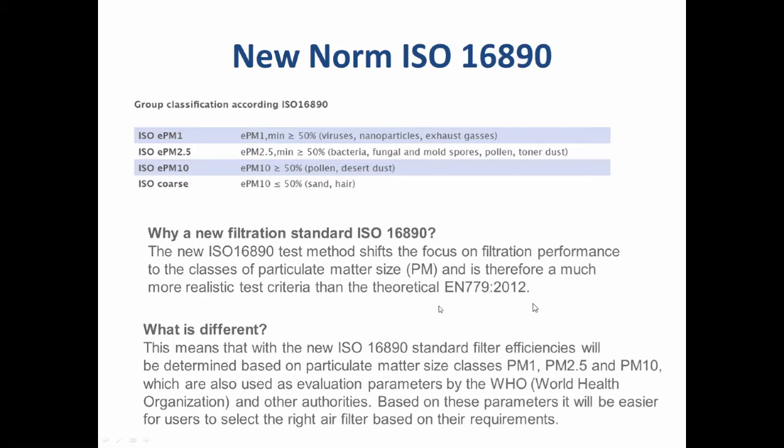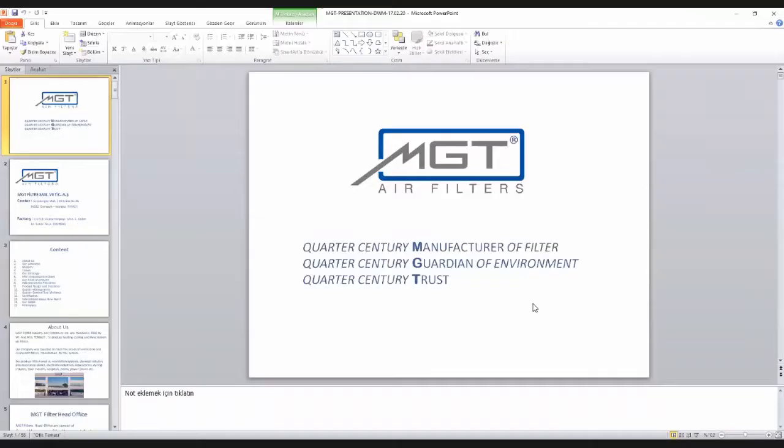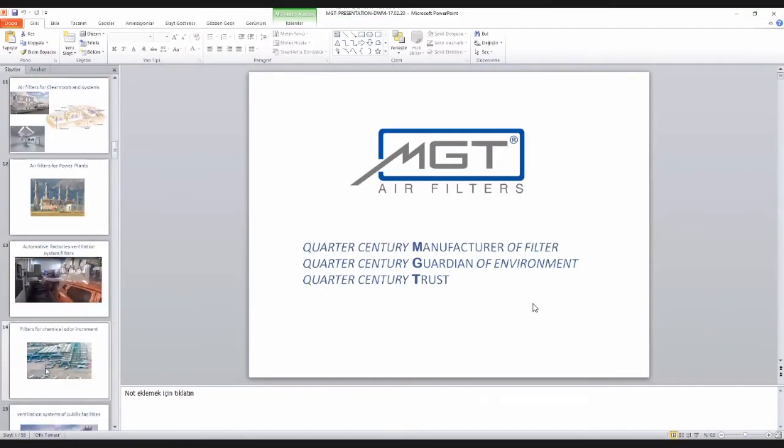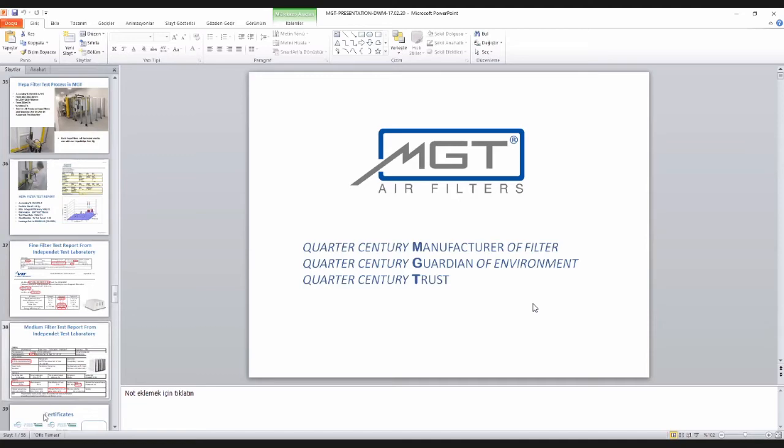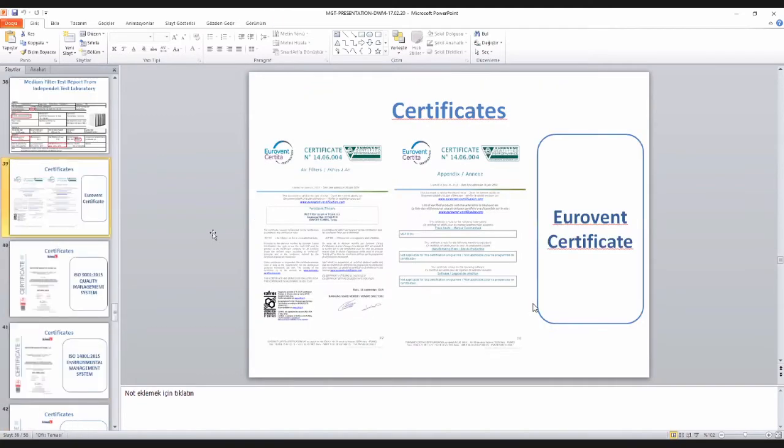But for the steel or HEPA filters, it depends where they use. Pharmaceutical companies mostly use aluminum frame, and food industry they use stainless steel frame. So it has to be stainless steel because of humidity in the places where they produce food or milk or whatever.